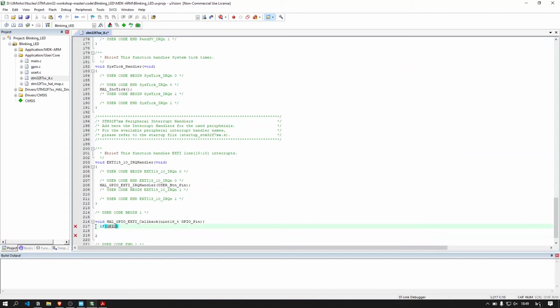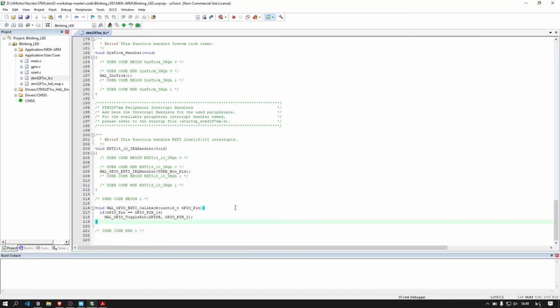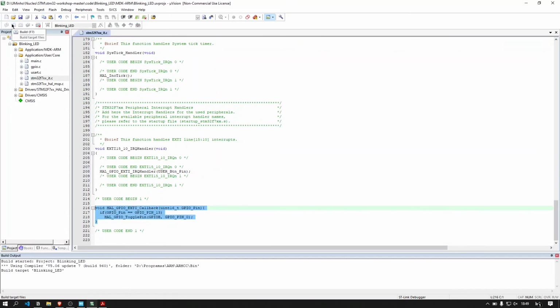If you activate two interrupts from pins with the same number on different ports, it will be the same ISR that responds. Also, the EXTI only has 11 lines, so from pin 11 to 15, everything goes to the same interrupt. One way to differentiate between these pins is to use this if. Let's compile and flash to see what happens.